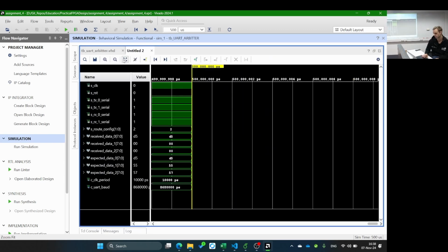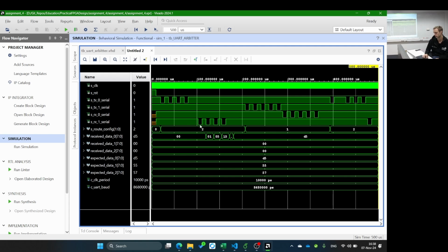Now you can see we have 500 microseconds, and then this will automatically run my full simulation. Well, almost full here. I gave it the wrong time, but essentially let it run until the end. The other part is the configuration, which are the settings in Vivado itself. Of course, they can also be scriptified with a Tcl script, whatever you prefer. There are many commands which let you put certain settings into a Tcl script automatically, and then you adapt that so you do not have to change anything or write anything from scratch, really.